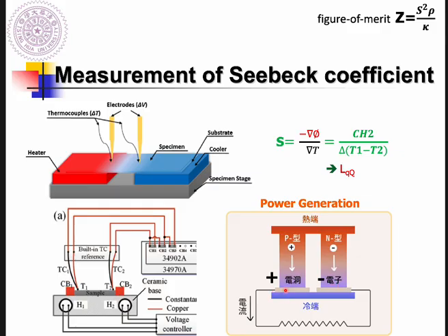So based on this, you see we have a higher electrical potential and a lower electrical potential, and that will lead to current passing through this resistance. So the driving force actually is a temperature gradient allowing the major carriers with higher energy to move downward to the location with lower energy. So this is the whole working mechanism.